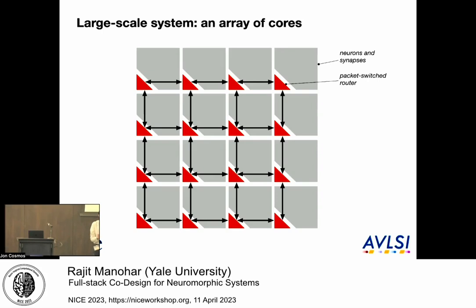For example, in some of the benchmarks done very early on in the TrueNorth evaluation, people said, well, we can beat your power by a huge factor with this new core idea or this new device. And I had to point out that half my power on that benchmark was actually switching the pads of the chip, which has nothing to do with the computation. It's just getting data on chip. So if you can find a way to make that even 20% better, you'll put everybody out of business. So accounting for everything is really important.